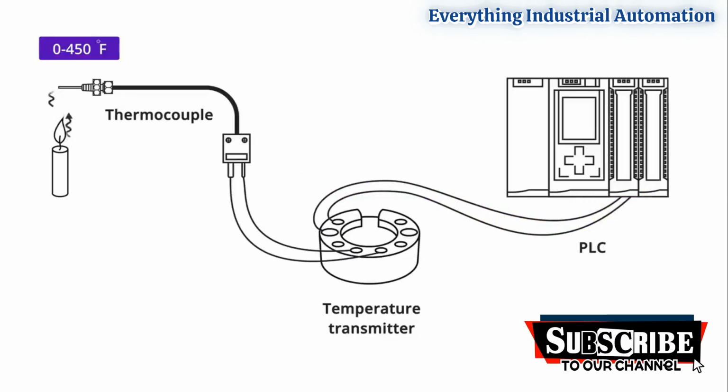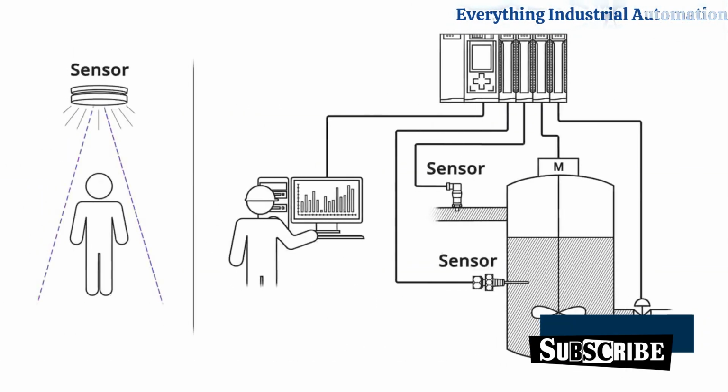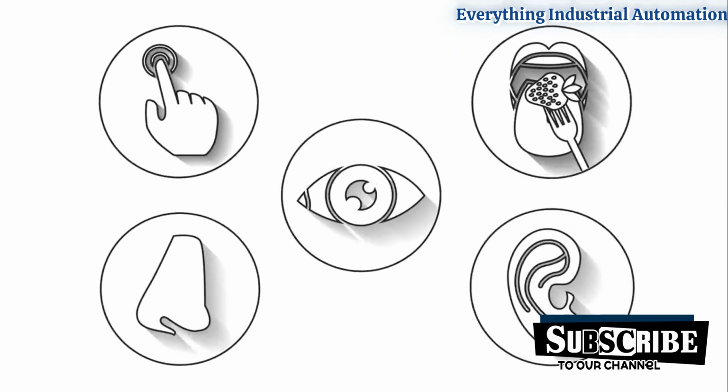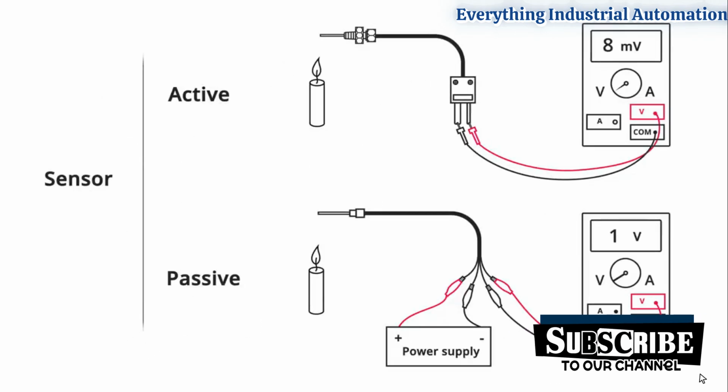Let's review what we've covered today. Sensors are a part of everyday life at home and work. A sensor is a device that can see, feel, hear, smell, and even taste. In process control, sensors are classified as passive, requiring an external excitation to produce an electrical output, or active, producing a voltage output without any external excitation.